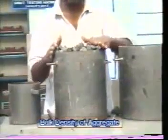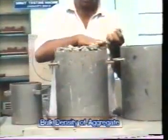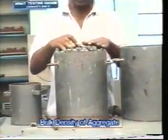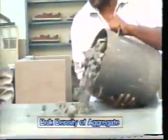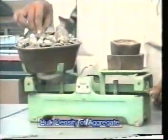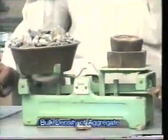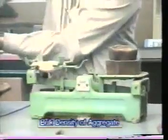After filling, level the surface of the filled measure neatly to flush with the sides of the measure. Now weigh the sample of the aggregate filled in the measure and report the bulk density of aggregate as weight of sample of aggregates in the measure divided by its volume.